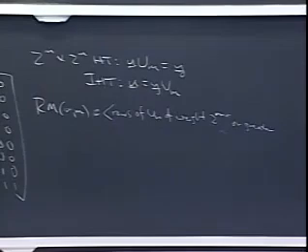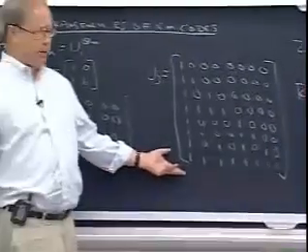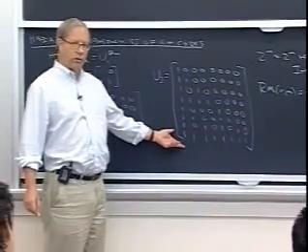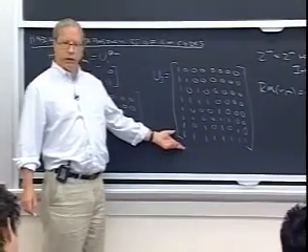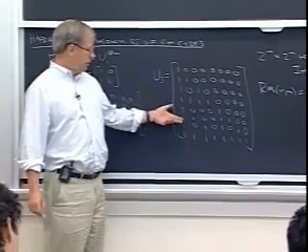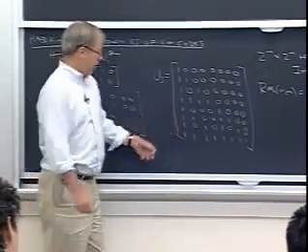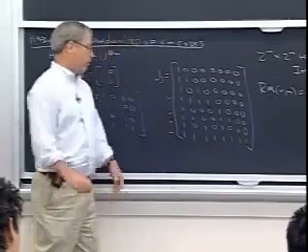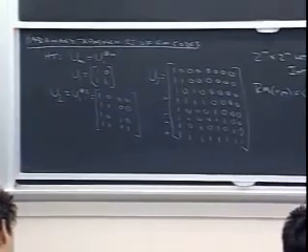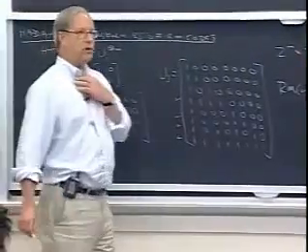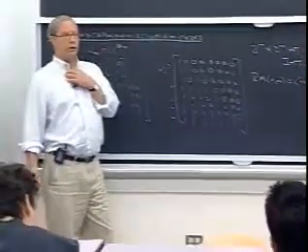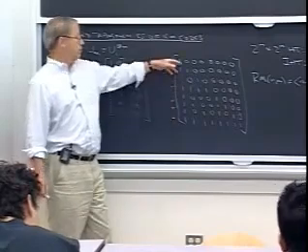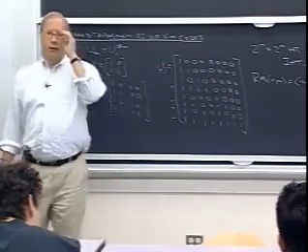So, for instance, the zero-order Reed-Muller code of length 8 is simply the (8,1,8) repetition code, and it's generated by this last row. It's the only one of weight 8. If we want the Reed-Muller code of length 8 and minimum distance 4, we take this, this, and this as our 4 generator rows, and we get the (8,4,4) code that we've been mostly using for examples. If we want the single parity check code of length 8, the (8,7,2) code, we take all these 7 generators, every one except for the unique weight 1 generator up here.